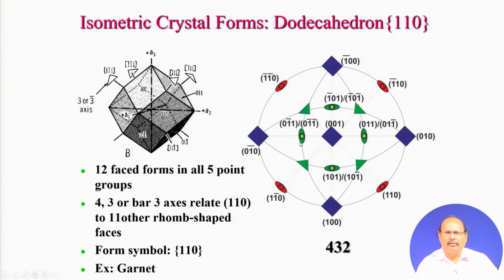And what is the name of this crystal face? This lies between this point here and this face here. This face is 0 0 1, this is 0 -1 0. By using the additive rule here, you will have 0 -1 1 here. So, this is 0 -1 1. So, all this has intersected the positive direction of the A3 axis.